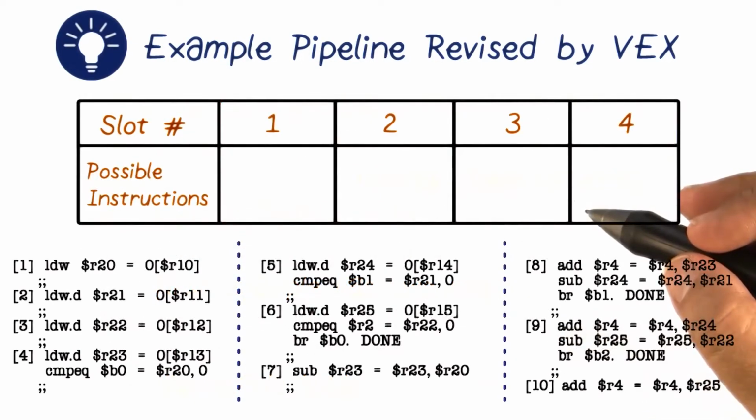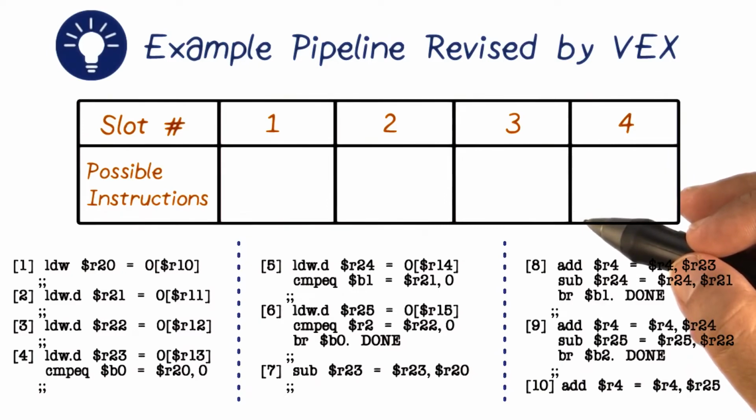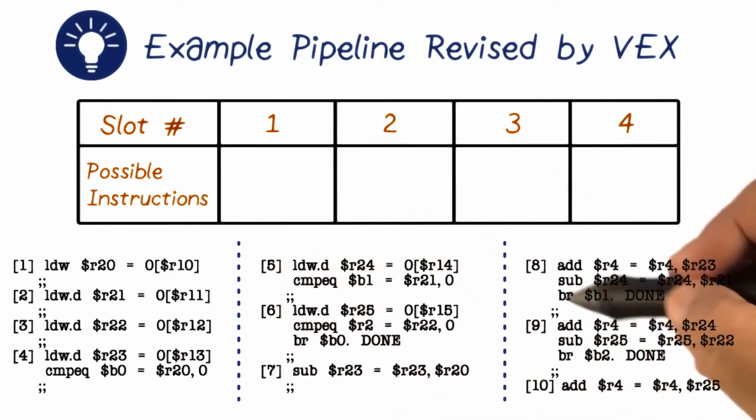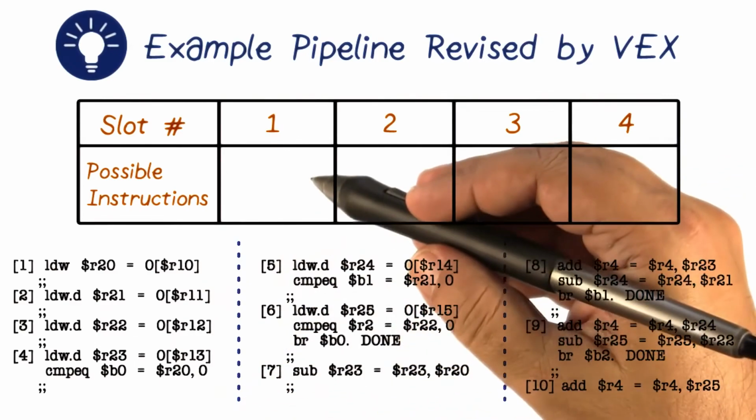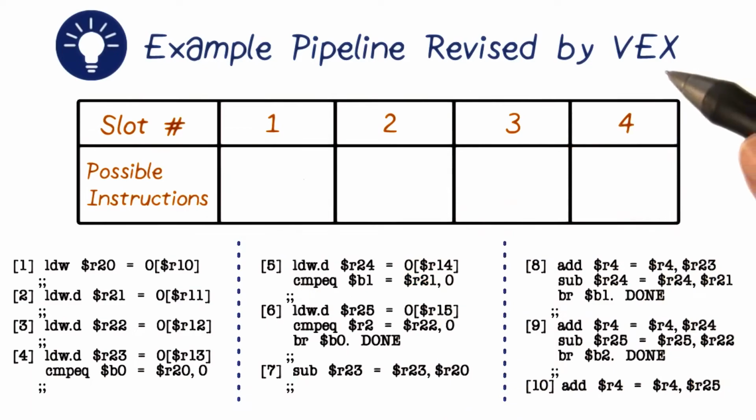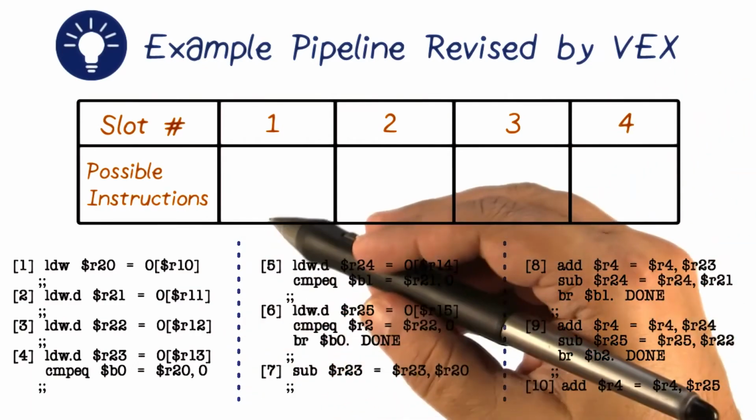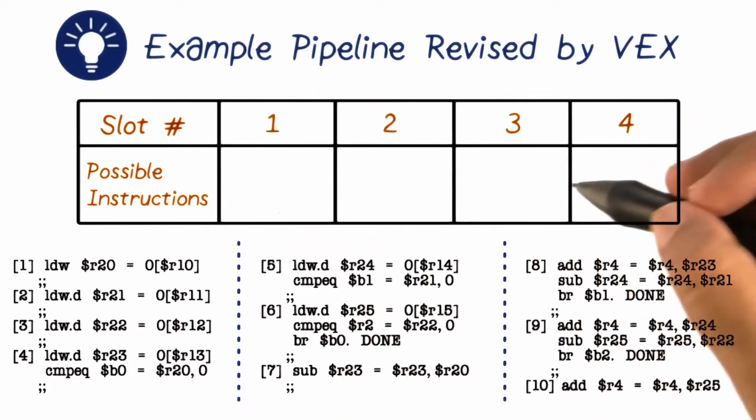Let us now consider the parallelism part of this example for the VEX architecture. You can see a program in the instructions here. As you can see, we can have a maximum of 4 sub-instructions inside an instruction. Each instruction executes in a given slot. Slots execute sequentially, that is, slot 1 executes, then it is followed by slot 2, then slot 3, and so on. So the question is how these instructions can be placed in these slots for maximizing their parallelism, or minimizing the time that it takes for this program to execute.